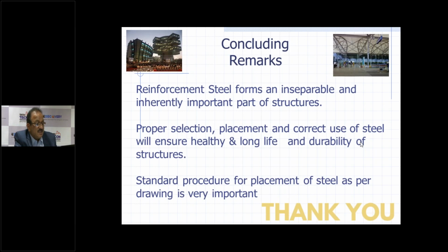I would recommend that. Now this is the last question I am taking, from Charanpreet Kaur. He wants to know, can we provide additional reinforcement for reducing the bending and shear force? Is there any IS specification for that? See, additional reinforcement is not going to help you, because in the design it is always preferred that we provide an under reinforced section rather than an over reinforced section, because in an over reinforced section there is a sudden failure.